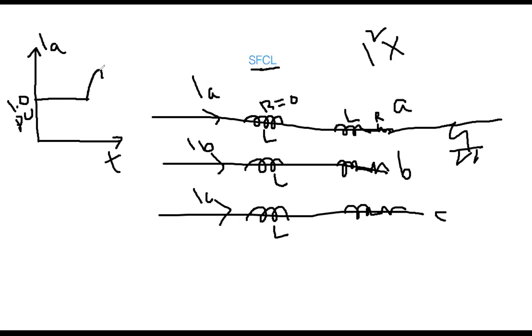The increased current is flowing through this SFCL. Even though there is a refrigerator, that current is flowing. Therefore, depending on the current magnitude, it might happen that it is no more a superconductor. It fails. It cannot maintain R equal to 0 even though there is a refrigerator, because suddenly the current magnitude may be 2 times, 3 times, or 4 times higher. Depending on this increased current, the superconductivity fails.